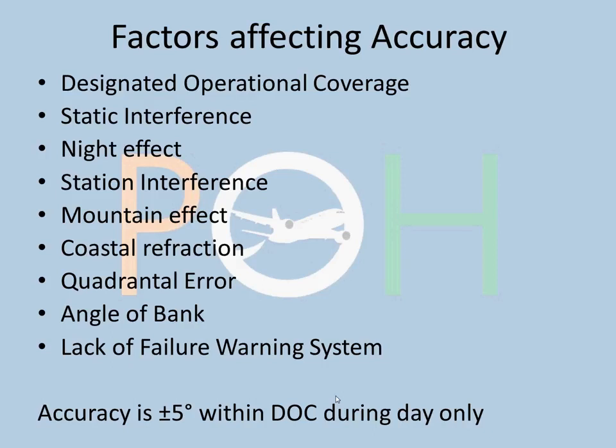Static interference is pretty simple. Precipitation, thunderstorms, or any electrical activity in the atmosphere will disturb the frequencies, because it collides with the water droplets or static electricity discharge, which affect the LF and MF frequency. That will make the needle move rapidly and will not give you any bearing at all.